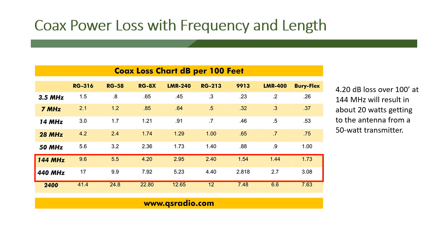So in my case, at home, I have about a 75-foot run to my antenna. So therefore, I chose, based on what I could afford, to have LMR 400, which is a low-loss coax cable at that range. I do a lot of HF work, so you can look up the 3.5, 7, 14, and 28 megahertz areas, and you can see it's got a lot of low loss, which means I'm not losing as much power in dB to the transmission line. And so therefore, I prefer that kind of cable. I want to get the most amount of power to my antenna as I can. Again, it's a more expensive cable. Could you use a cheaper cable? Absolutely.